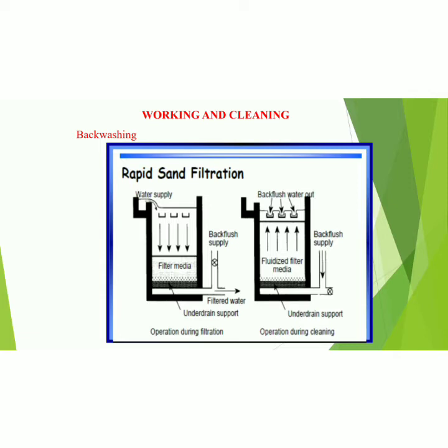So in the reverse direction they will flow the water such that all the impurities which are present in the pores of the sand will again get collected and mixed with water, and finally that water is removed through water troughs, which you can see in the second diagram, where at the top they have written back flush water out. From there the water gets collected with the impurities and is drained off. So that is the general idea of backwashing. I will show the video later.